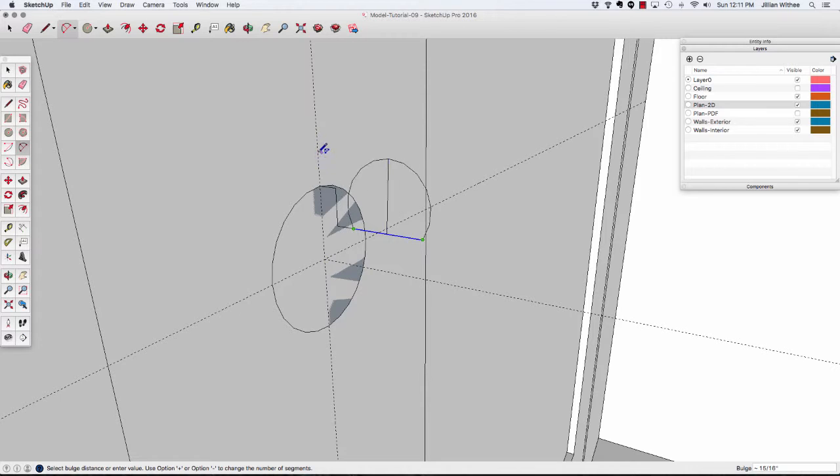Oops, why didn't that work? Let's see. 0.5, enter. There we go. And then I'm going to go ahead and delete that bottom line right there. And then on the edge of our arc, we are just going to drag down to that center line that we created, come across over to the center line of the back, the center point of the back plate, and then up. That closes our loop so that we get a face. And now we can revolve that face.